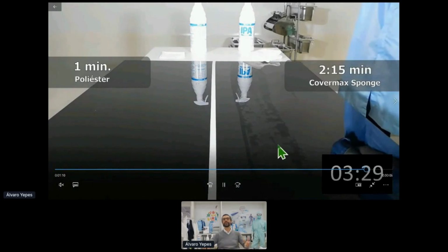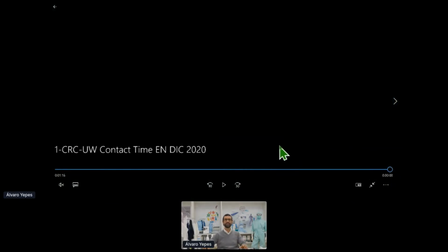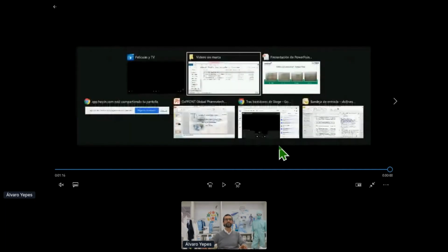So remember that we mentioned that depending on the biocide or depending on the risk of the actual process you have, this can be a critical factor to think about. If you use, for example, hypochlorous or a bleach molecule that are fast-acting, especially hypochlorous acid, you may not require the same length of contact time as if you go, for example, with hydrogen peroxide 6% or glutaraldehyde molecules.